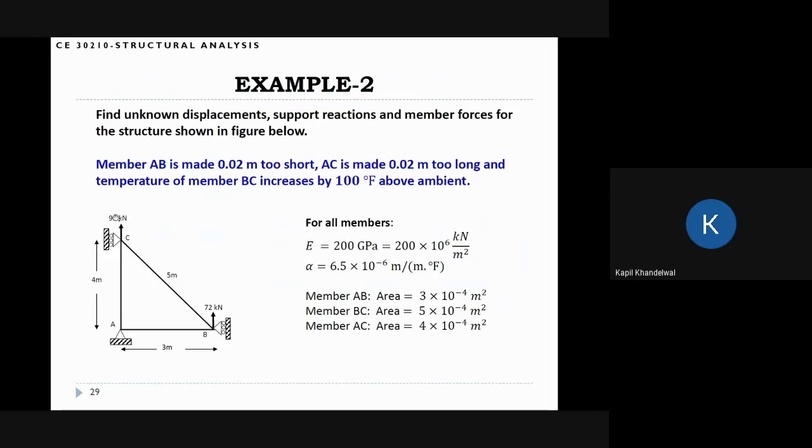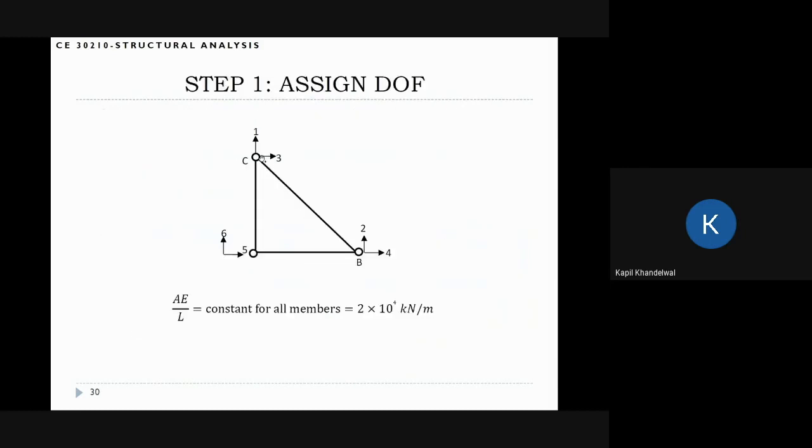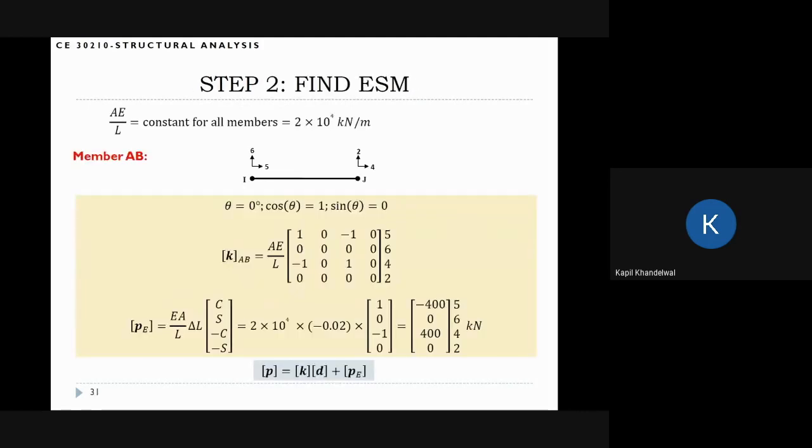One is this vertical motion here. The second is this vertical motion here. All the other degrees of freedom are supported. So I label the free degrees of freedom first. So this is U1, U2. And then I can just go in any order. So I'm saying this is U3, U4, U5, U6. So this is the degrees of freedom labeling for the system. I again want to emphasize that I have labeled for the truss the free degrees of freedom first.